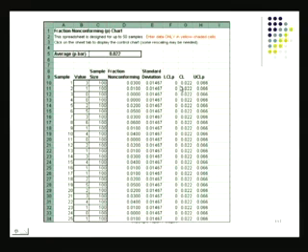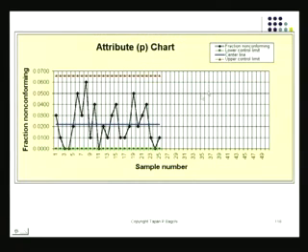I open the book, I plug in the right quantities. I refer to some cells where I've got the references, and I'm able to get my control limits. Once I have my control limits, I have my regular reading there. I can do my comparison quite easily. Once I do that, I can construct my P chart without any trouble at all.